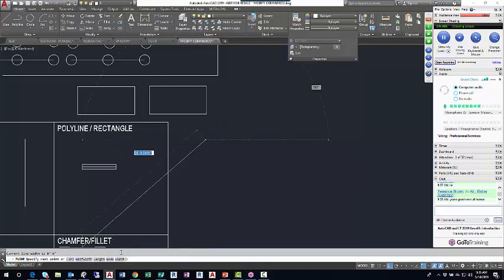I can change the width of the polyline and so forth. So the command line options are what would really qualify this as an advanced draw command. I'll move to the right, left click my next point, then I'll come down on the command line and click arc. Now I'm creating an arc shape. Ortho is on, so it's being very rigid with how I create this arc shape. It actually keeps you in arc mode, and these arcs will switch back and forth as you're drawing them.